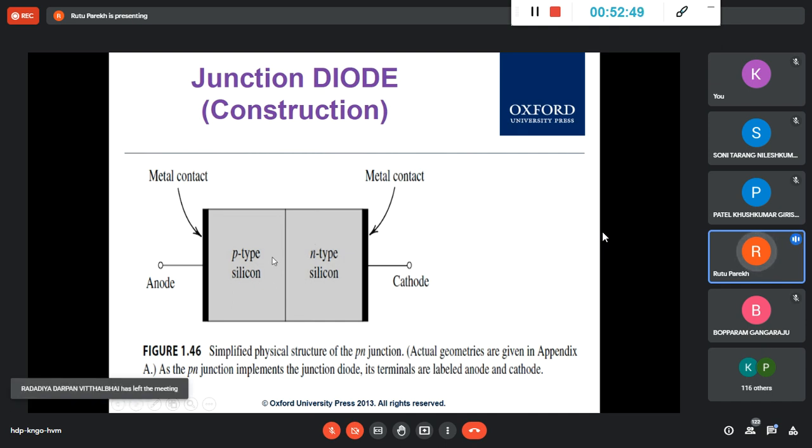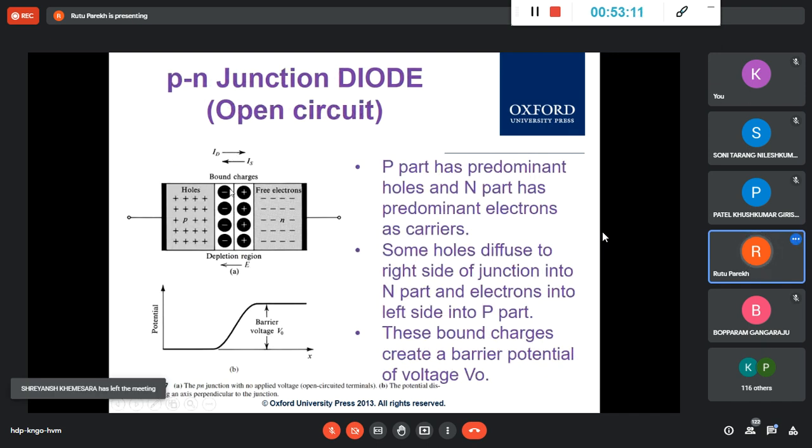But after that, these are more in number here, and these are more in number here. Some recombination happened initially. And then some electrons are still moving because of the diffusion. Few of them got recombined, but there are so many that the holes, because of the diffusion, will come and settle here, and the electrons will come and settle here. And these are known as uncovered charges. The ones that combine are covered charges.